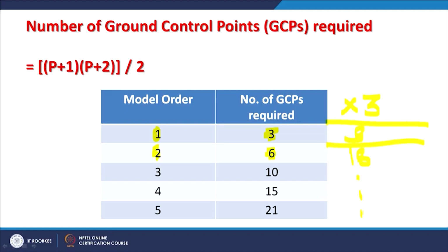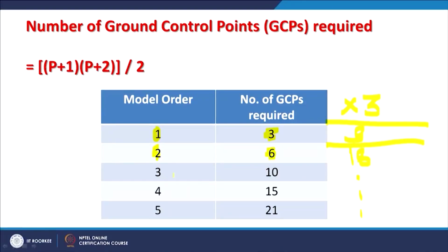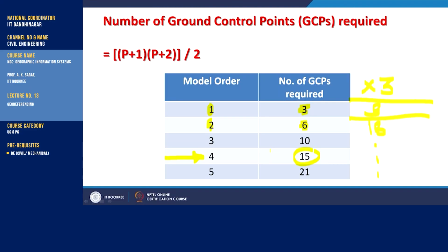So, if I do not require more than third order, why should I go higher? Because most of these geometric distortions introduced by satellite images or drone can be resolved maximum up to third order in most cases. If a situation, like in the case of a drone, has wind speed and other factors while the still image is acquired, then probably fourth order may be sufficient. But again, finding reliable common ground control points in both images, input and master, may be very challenging.